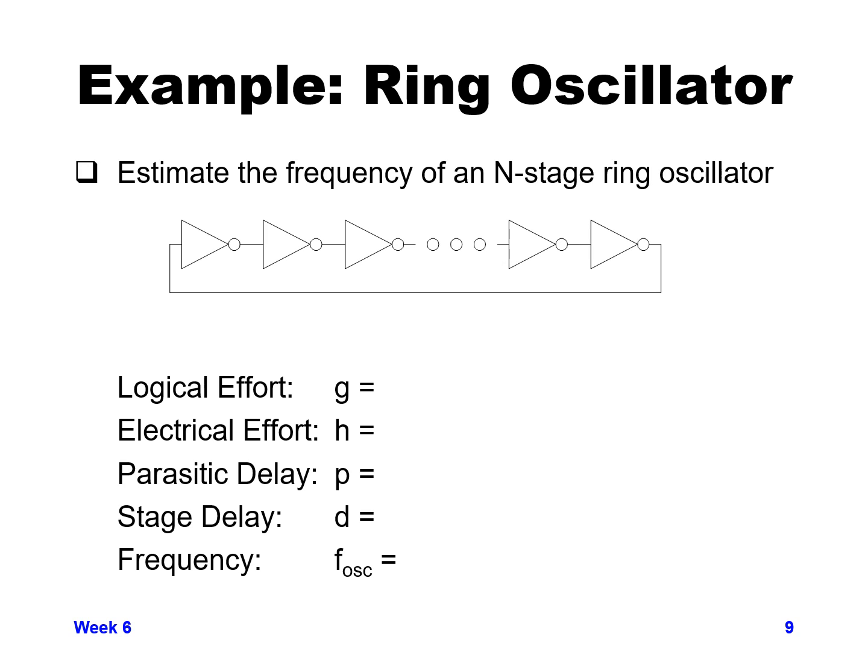So hopefully you've figured it out. Let's go through and determine each of the values here. Our logical effort, G, is 1, 3 over 3 for basic inverters. So by definition, G is 1. Electrical effort, that is what the fanout is. In this particular case, each inverter is just driving one other inverter, so H is 1. Parasitic delay, for a basic inverter, is 1. So our overall delay is going to be G times H plus P. That gives us 2.